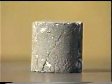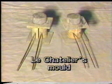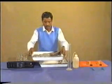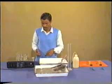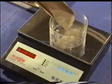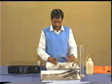The test of soundness is conducted with the help of Le Chatelier's mold. Measure 100 grams of cement sample. Place the sample in the enamel tray.